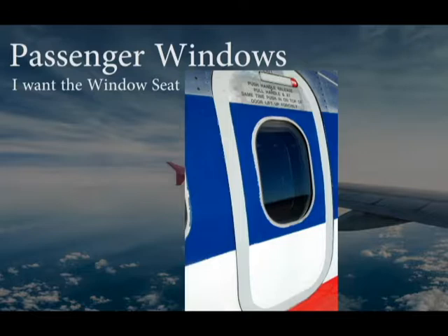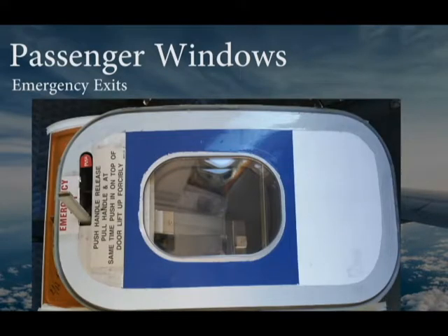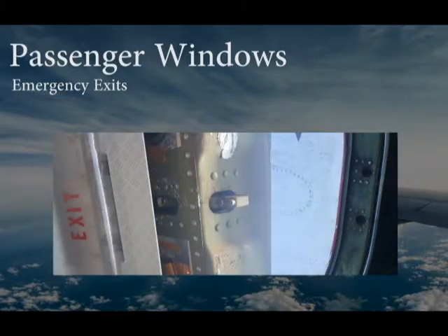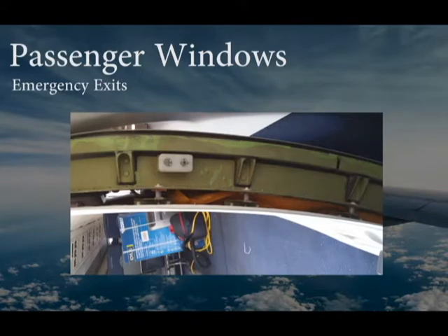Also in the cabin area are the side emergency doors. The side emergency doors are somewhat similar to the main doors in the way they're sealed. When in the closed and locked position, the doors are pressed outward by the pressure difference. The emergency exit doors are placed on the aircraft in locations that allow a flow of passenger traffic to exit quickly. Emergency exit doors become detached when the emergency mechanism is utilized. The opening mechanism is a rotating lever that disengages the hinges, allowing the door to be lifted up and away. This allows the doors to be moved out of the way of exiting traffic in the case of an emergency. These doors weigh about 40 to 50 pounds, so a moderately fit person should be able to remove the doors without complication, especially with adrenaline helping since it's an emergency.